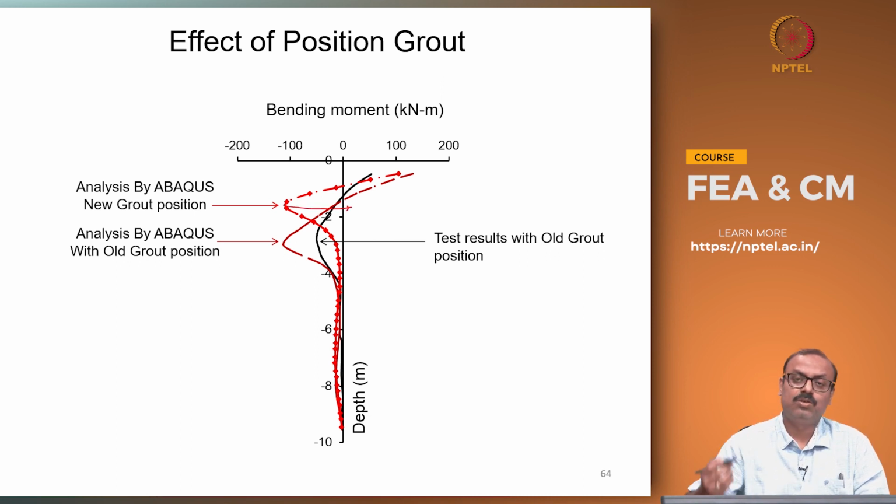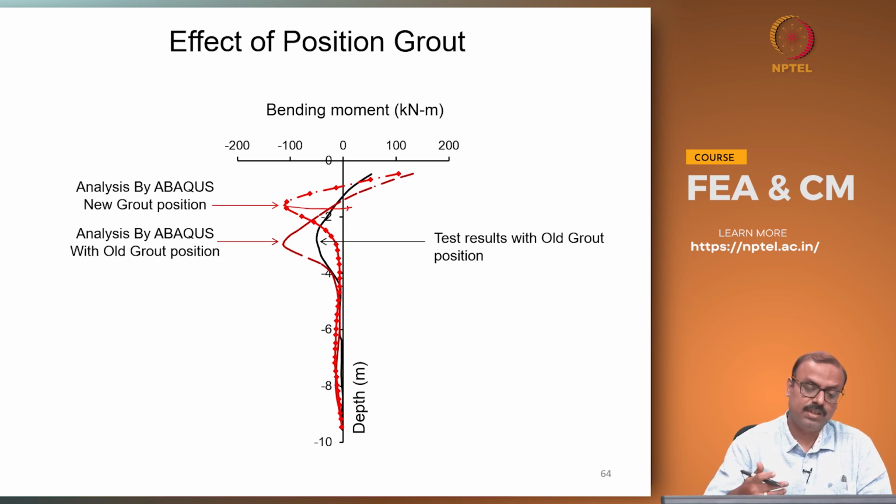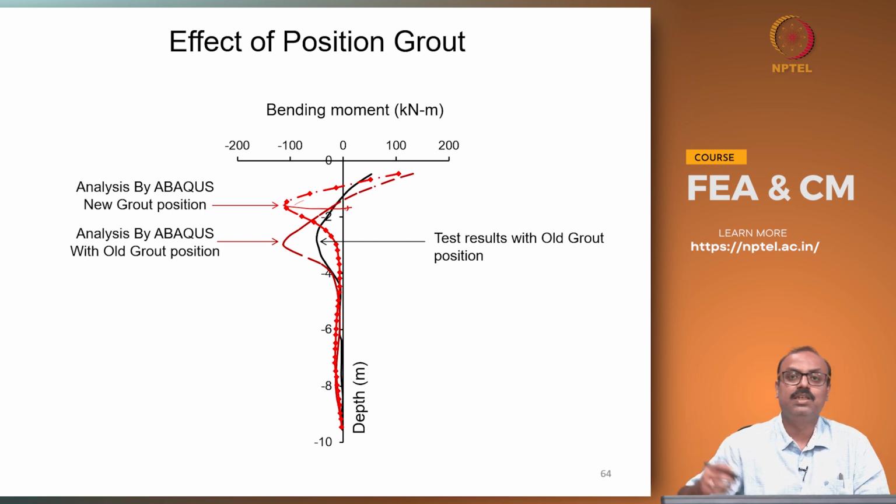So, it shows that the reinforcement body is giving a kind of fixity around the pile, so the bending moment development is localized to that region. One of the major advantages of getting these results is that the structural design of the pile can be done based on this. So, it can be done locally to avoid any kind of flexural failure, where we can have additional steel.